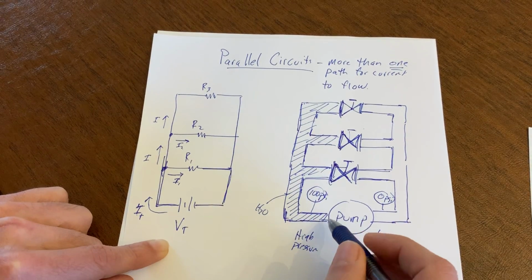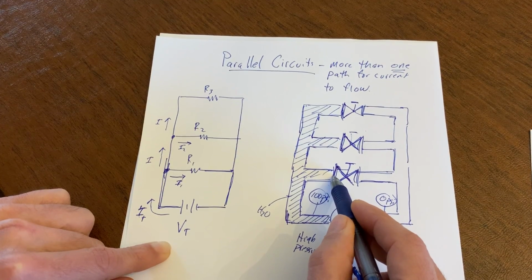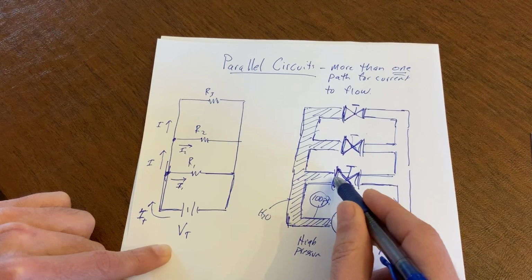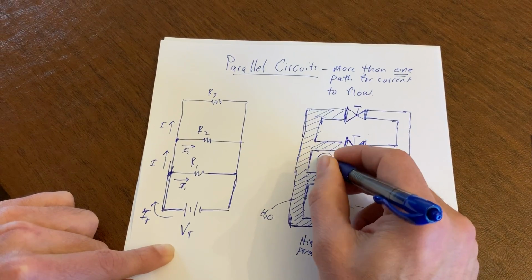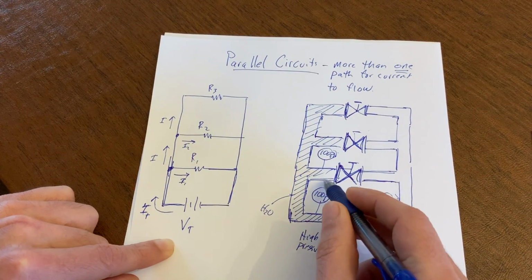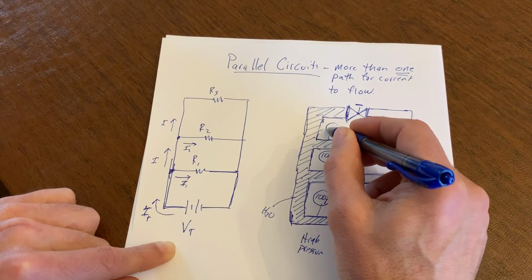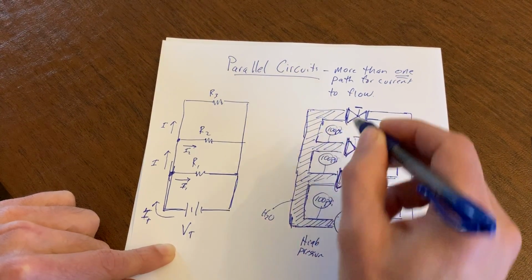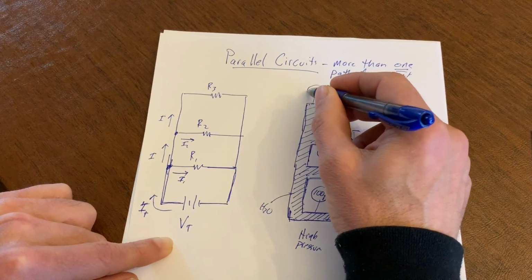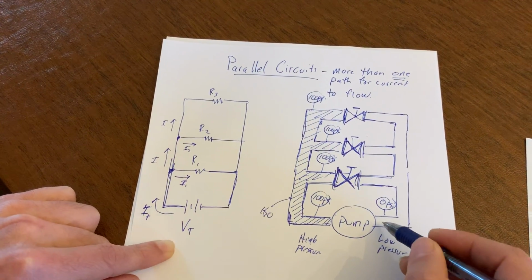If it's full of water, wouldn't you see that the high side of the pump is connected to that side of my valve? If this is 100 psi and it's connected via a pipe, I'm going to say that this side right here is also at 100 psi. Let's say this side is still connected by pipes full of water. What's my pressure here? Lo and behold, it's also 100 psi. And what about up here at this valve? Guess what? It's also going to be 100 psi. How about this side over here? Well, there's nothing in here.